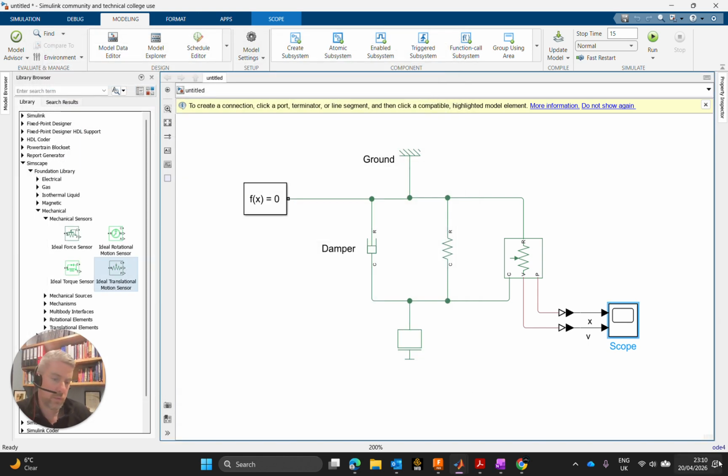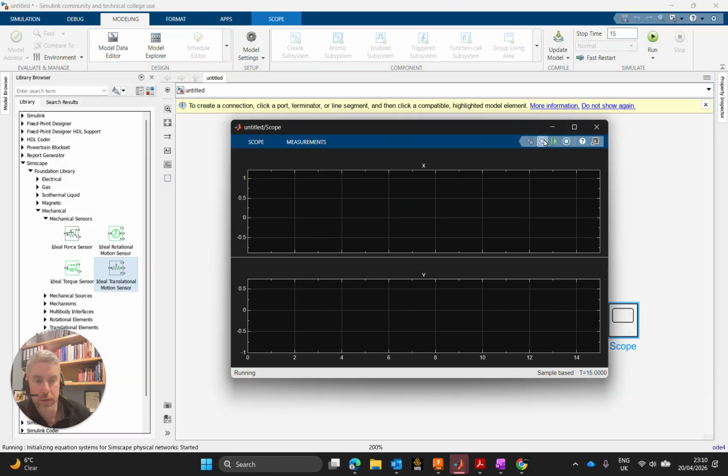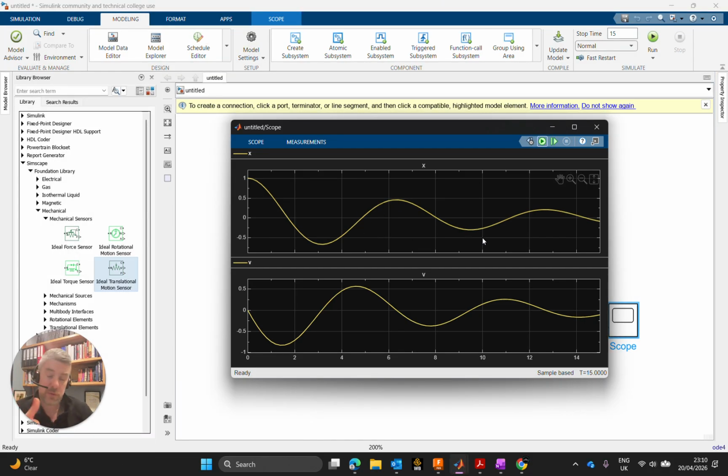Okay, so now we're running Runge Kutta 4. And just run it from the scope, and let's run that out again. And there's our step, so it looks nearly identical, the same. So you'd say, well, should I run Runge Kutta 4 or ODE 45? Should I use a fixed time step or use the defaulted ODE 45 Dormand-Prince variable time step solver?